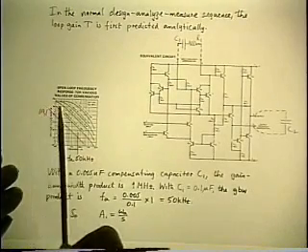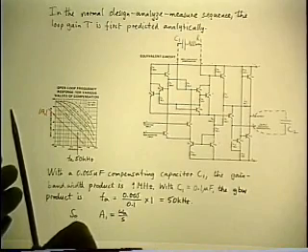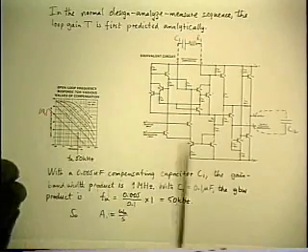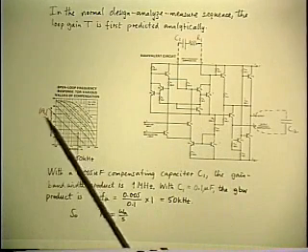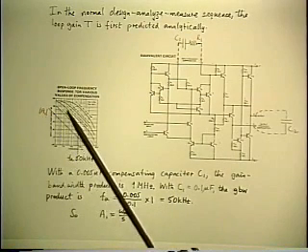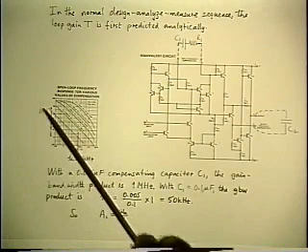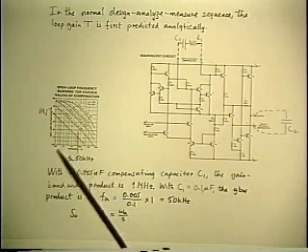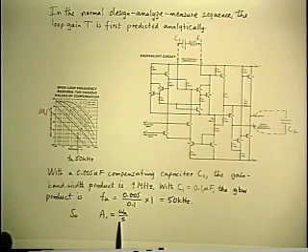I don't care about the fact that the zero frequency gain will be finite. I'm not interested in it. The only important part of it from the point of view of the loop properties is what happens around crossover. So I don't need to write an equation that represents the gain of the op amp all the way down to zero frequency. All I need is an equation that represents this asymptote, which is going to influence things near crossover. And that's the standard single slope that we've done lots of times already.